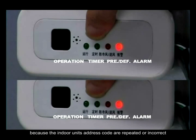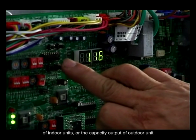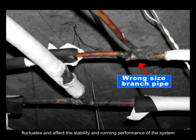Because the indoor units' address codes are repeated or incorrect, the capacity output of the outdoor unit is not matched with the required load of the indoor units, or the capacity output of the outdoor unit fluctuates and affects the stability and running performance of the system.